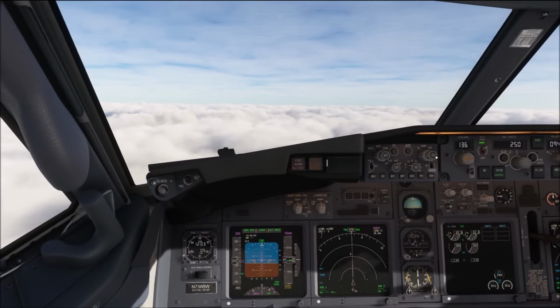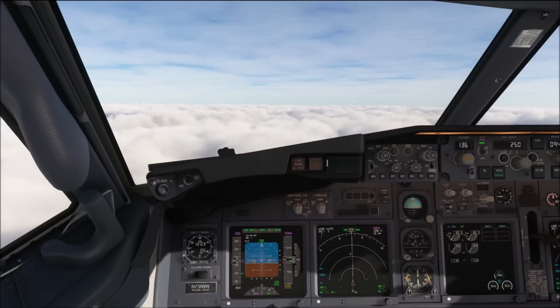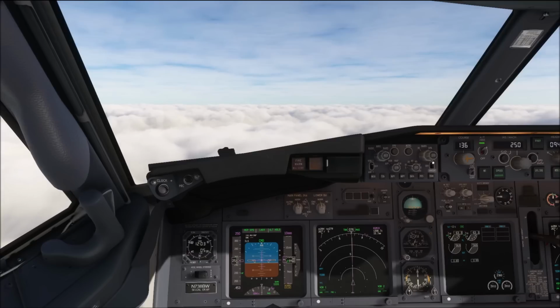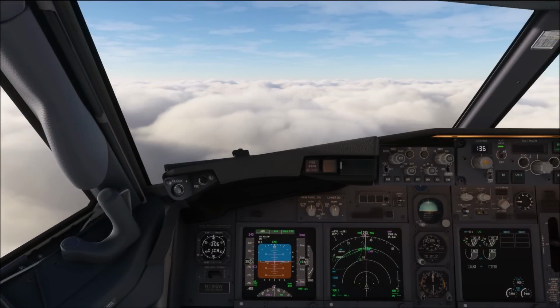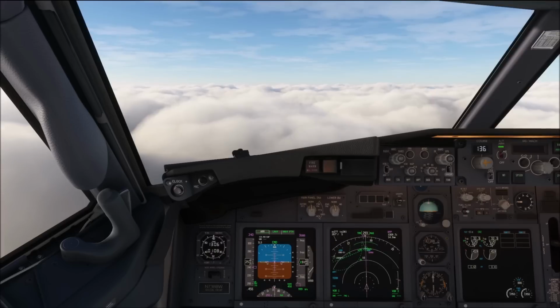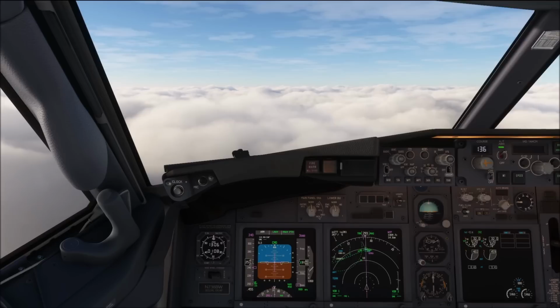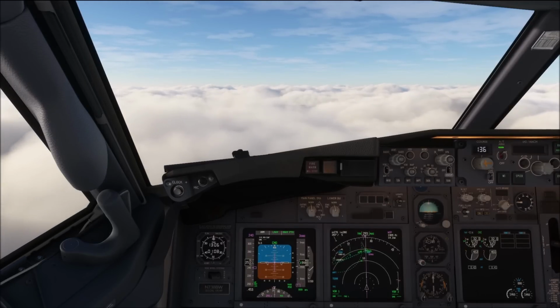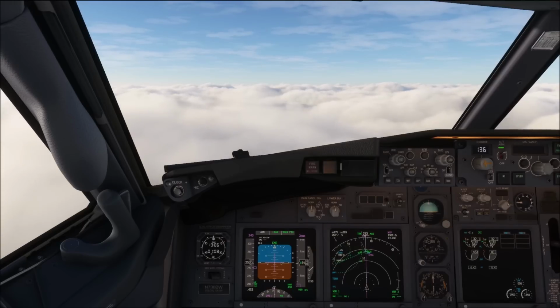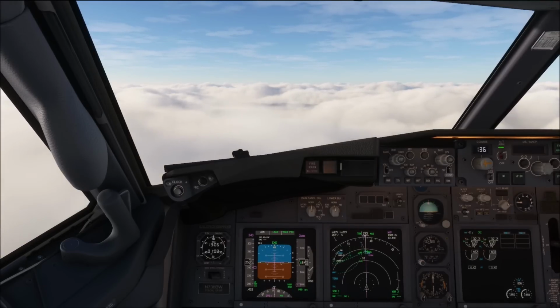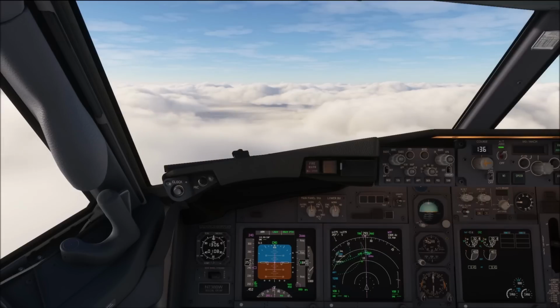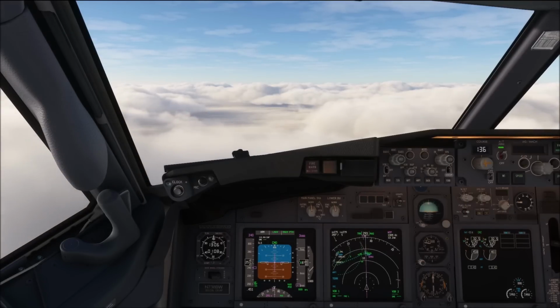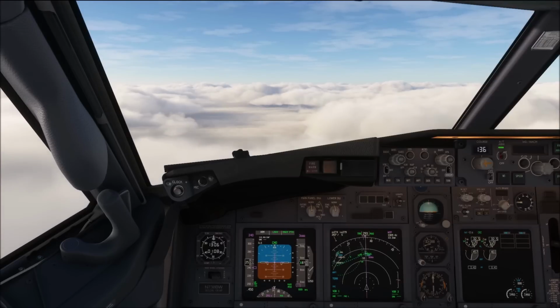This will conclude the current look at our departure, so let's just go ahead for the purpose of a demonstration and look at the arrival procedures as well. Welcome back a little bit later throughout the day, and we are now flying back towards Cologne and have just started our descent towards VIPA from where we are going to fly a standard ILS approach for runway 14 left. Weather conditions in Cologne have still not improved, so we still have snow, minus 5 degrees in limited visibility. So the weather conditions are just about within the Category 1 limits, so we are going to conduct an ILS Cat 1 approach into Cologne.